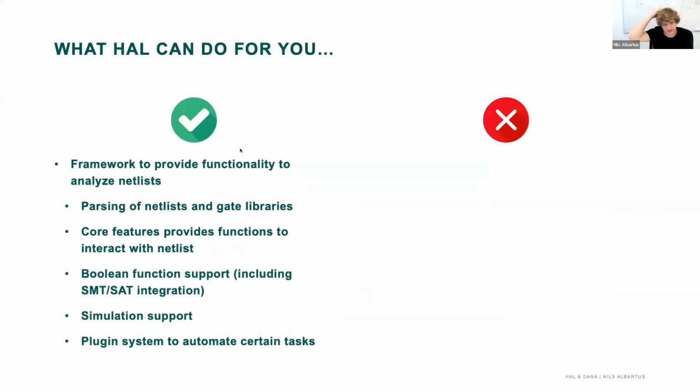So as a summary, this is what HEL can do for you. HEL is a framework that allows you to parse the netlist and gate libraries. HEL is technology independent, so as long as you have the gate library that belongs to your netlist, you can use HEL for your analysis.